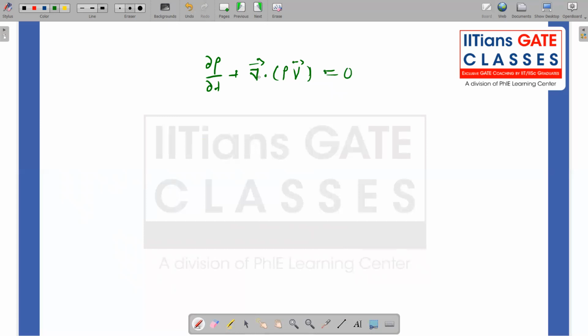So we cannot simply take del dot rho V as rho times del dot V. It is not correct. Most of the time people make this mistake. This is okay when we have an incompressible assumption with density being constant, but it need not be true in all cases. We have to understand that this is a vector operator which is operating on a scalar field and a vector field.